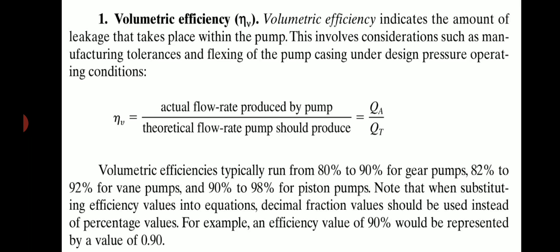Volumetric efficiency. Volumetric efficiency indicates the amount of leakage that takes place within the pump. This involves considerations such as manufacturing tolerances and flexing of the pump casing under design pressure operating conditions. Volumetric efficiency is equal to the ratio of actual flow rate produced by the pump to the theoretical flow rate the pump should produce, QA by QT.